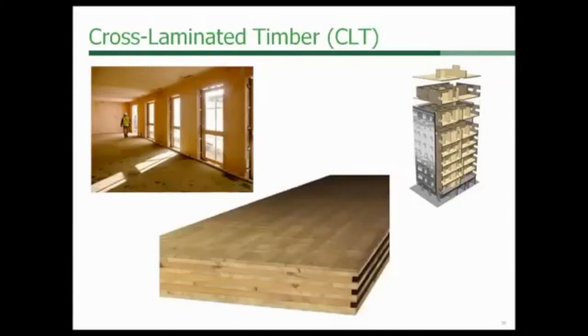Here is the product that is causing much conversation in regard to type 4. Because all of a sudden, cross-laminated timber is layers of dimension lumber or structural composite lumber laminated together in crosswise fashion. You see a picture of it here to make a solid wood floor or roof or wall section as you see it here.